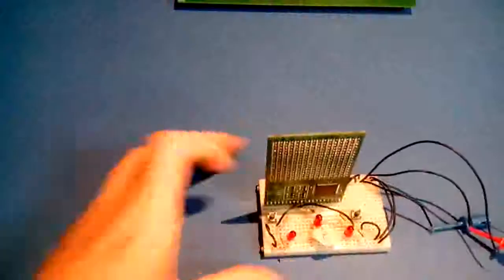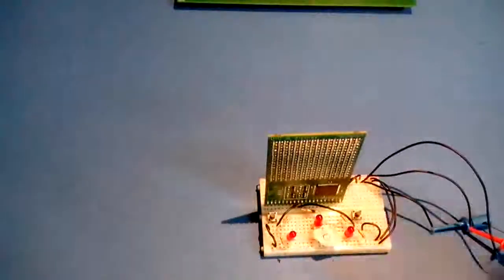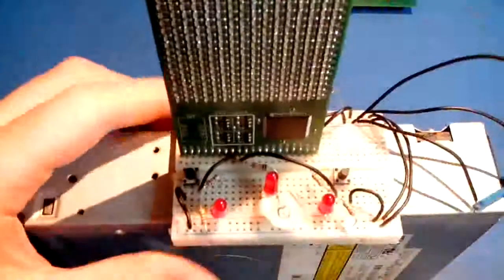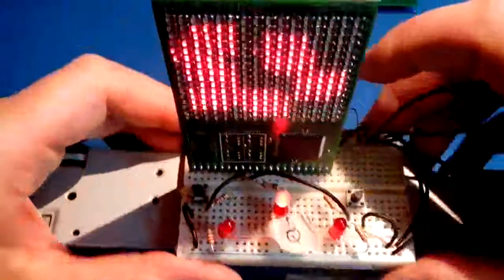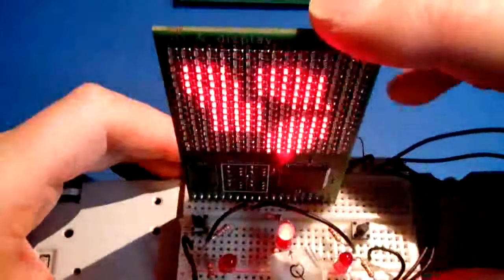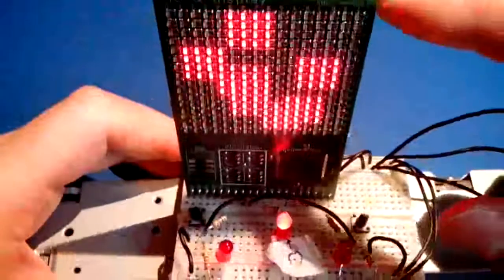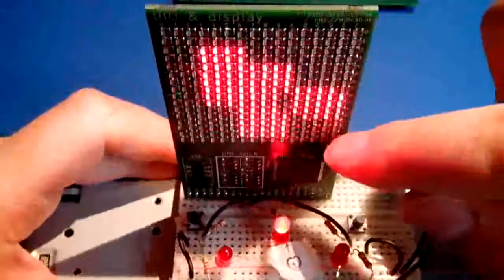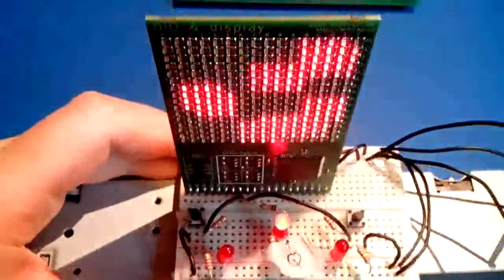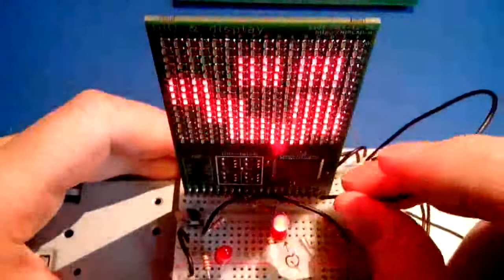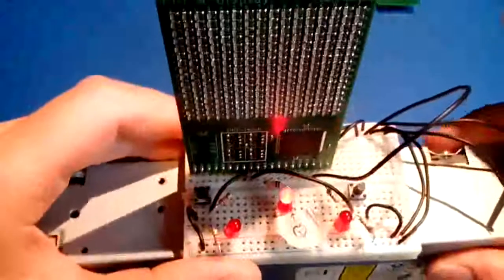Now, if we stick that on the breadboard like that and apply power and lift it up a bit so you can see what's going on. First thing is a nice distracting demo mode of the display. What the display is doing, if it's not receiving serial communication from somewhere else, is just doing a demo, just a test. This is very nice and also very distracting, so let's disable that by grounding the inverted reset pin of this display module, which we did just now.